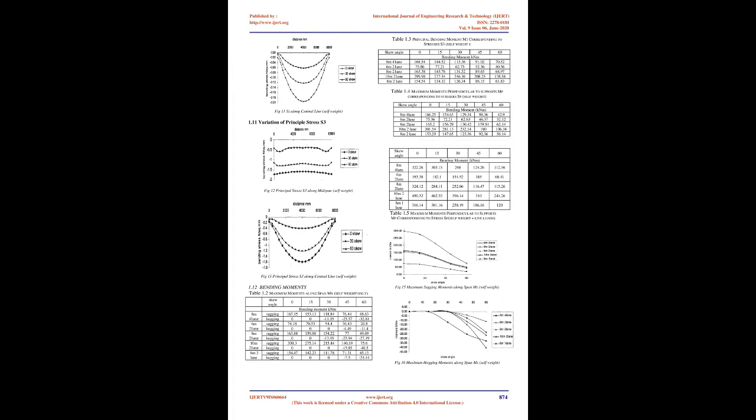The thickness of the bridge was taken as a uniform depth of 0.750 m. The meshing was kept the same: 8 layers of elements across the depth, 38 elements along the width and 16 elements along the span. Different spans and widths were considered to achieve different aspect ratios of length/width.